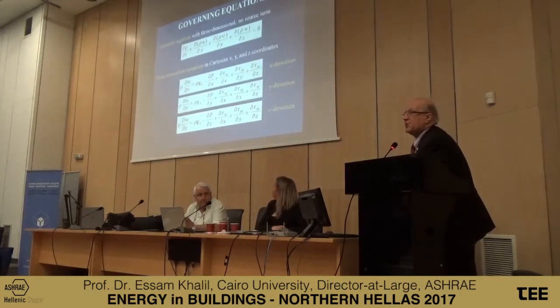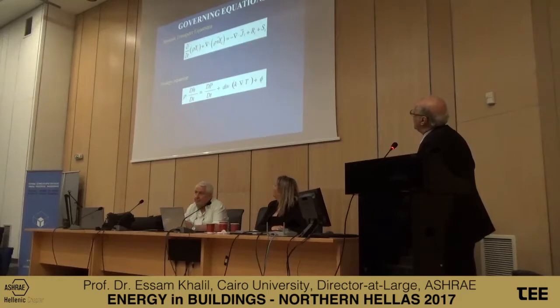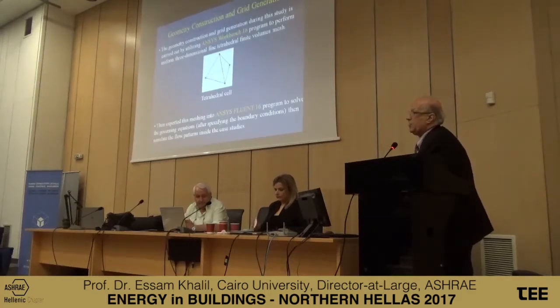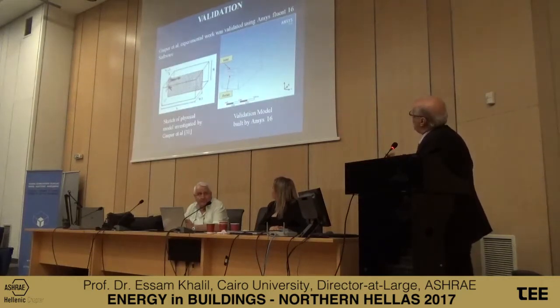These are the governing equations that you heard me talking about earlier today: the continuity and the three momentum equations in the three directions, taking into account the gravity, pressure, and various stresses. So this is the energy transport equation, and also the species transport equation. And we solve these on a network or a grid of points using commercial software.